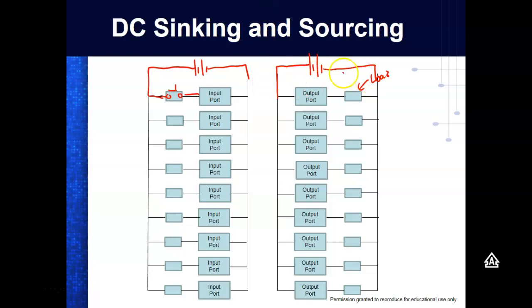So over here, if we're going to use DC outputs, the outputs are sourcing. That means what do I have to do? I have to wire all the outputs to the negative. So I have to hook up my outputs what?